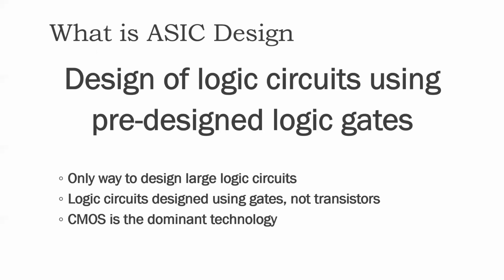However, in this class, that's not the meaning that we're going to use for the term ASIC. For us, ASIC design represents a kind of design methodology. In particular, what we mean by ASIC design is the design of logic circuits using pre-designed logic gates. This is the only way to design large logic circuits. The important thing is that the logic circuits are designed using gates, not transistors.